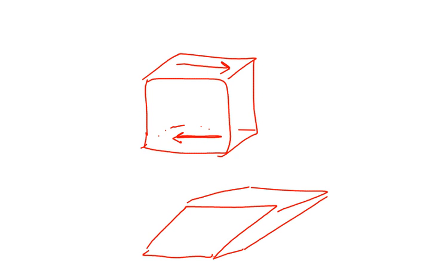Can everybody see that? Basically, if I look at this cube head on, it started off as a square, and then it became diamond-shaped, because there was this force pulling towards the right on the top surface, and then this force pulling towards the left on the bottom surface. So that's the deformation that shear stresses give you.